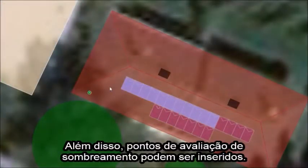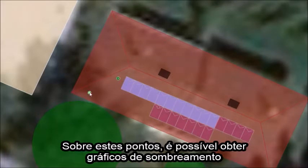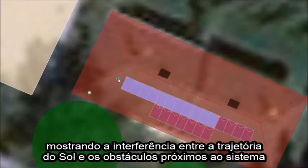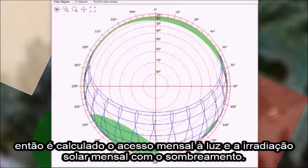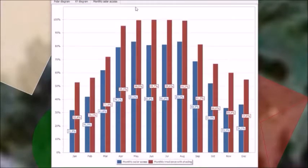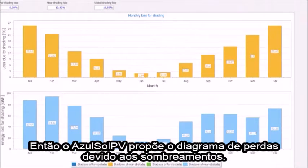In addition, shadow evaluation points can be entered. On these points it is possible to obtain shading graphs showing the interference between the sun path and the obstacles near the system, so the monthly solar access and the monthly irradiation with shading are calculated. So AzulSol proposes the loss diagrams due to shadowing.